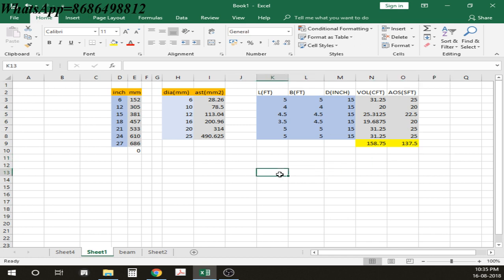I want to show you one last tip, which is the if statement. Like if someone is asking you whether the slab is a one-way slab or two-way slab, usually you judge it by the alpha, or Ly by Lx, ratio. Now here we go. I'm going to put here Ly, my longer direction, and here Lx, my shorter direction. Now I'm going to put here 6, and here, let us say, 4. Now please judge for yourself what kind of slab it is going to be. Obviously it's going to be a two-way slab, because 6 by 4 is 3 by 2, which is 1.5.